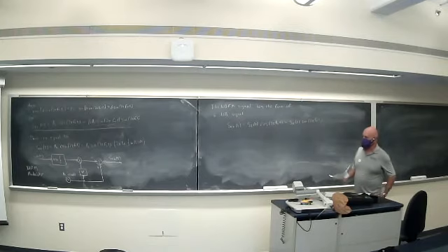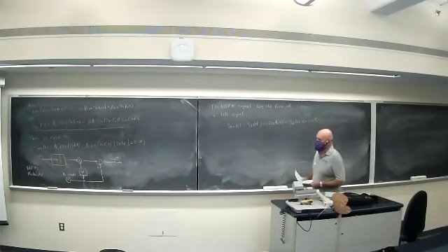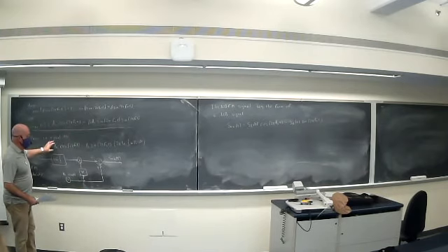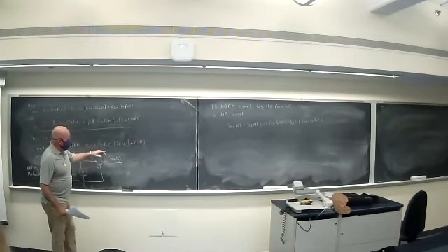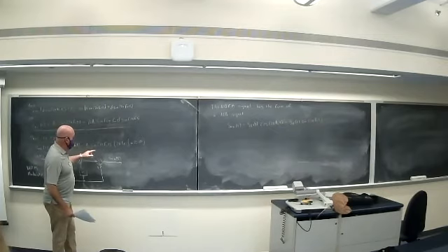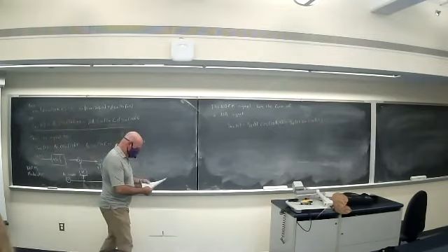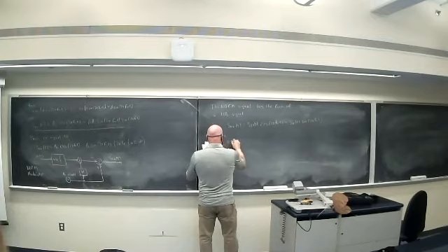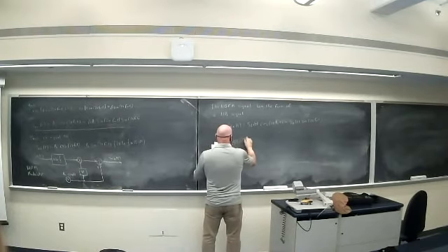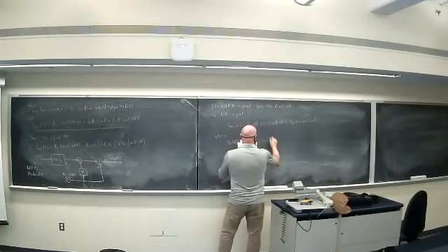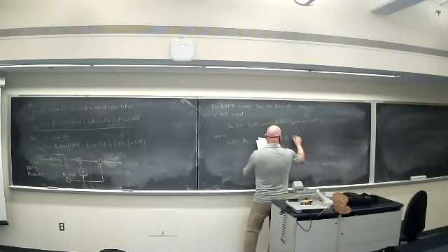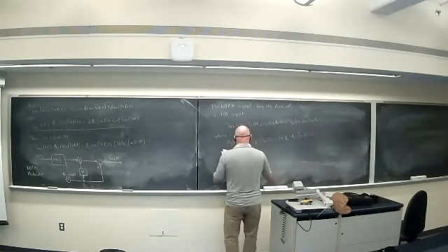We can actually use it even for wideband FM. But it certainly applies, and we can see it here in narrowband FM, where our sI term would just be Ac, and then our sQ term would be 2 pi kf Ac times the integral of our message. Okay.